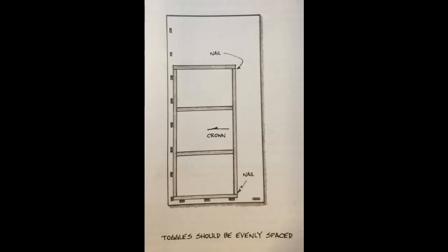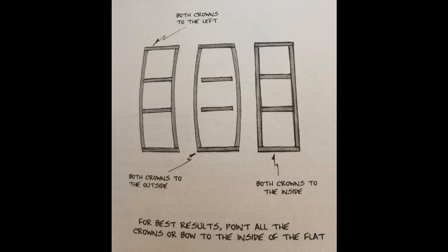This is also where some of the defects come into play, though. There are often times in which utilizing 1x4, which is often best for these walls as it keeps them fairly lightweight and easy to work with, you get a lot of the bows and or bends in the wood, as you see here in this picture here.